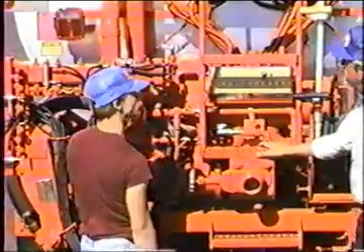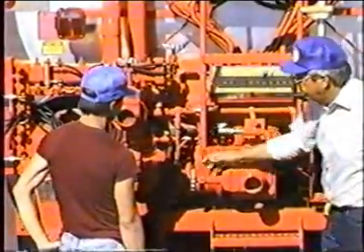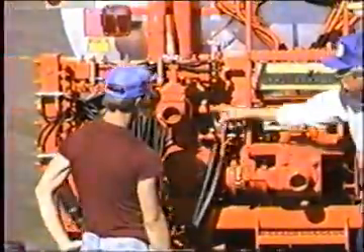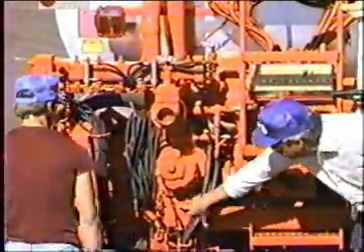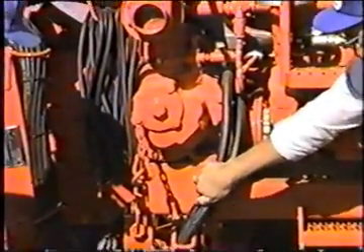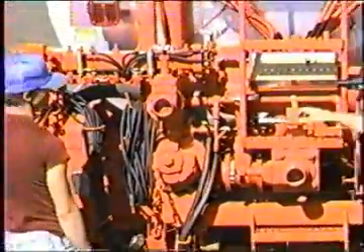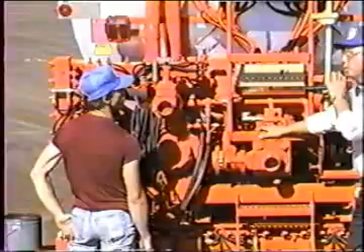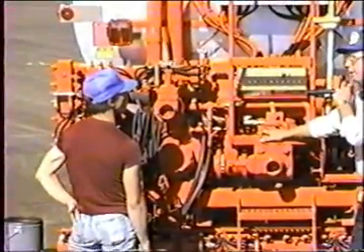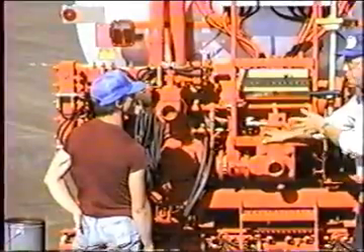Okay, in circulating the tank, we're coming into the strainer. We're going to go through that valve, going to go in the bottom of the pump and out the top. And if you look down on the bottom here, there's a plate that says asphalt pump. It says forward is in the bottom, out the top. Reverse is in the top and out the bottom. And of course that forward and reverse control is in the cab of the truck, and we'll talk a lot about that when we get up there. For right now, we'll just say we're going to run the pump forward.